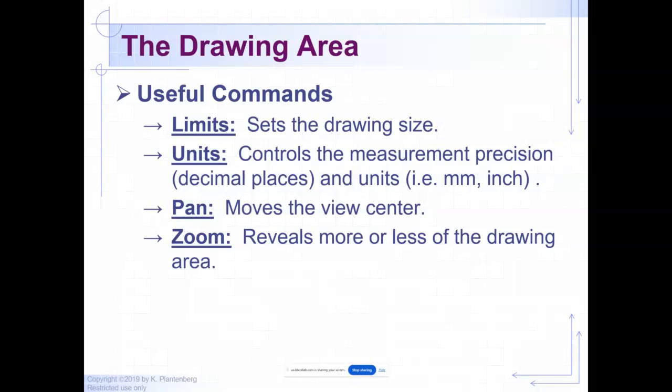My point being here, draw everything full size. At any time in any CAD program, everything is full size. The only time we scale anything is when we print it out or turn it into a document to give to somebody. That's where we actually scale things. And we'll get to that later on. Okay, so know how big your thing is that you're drawing.